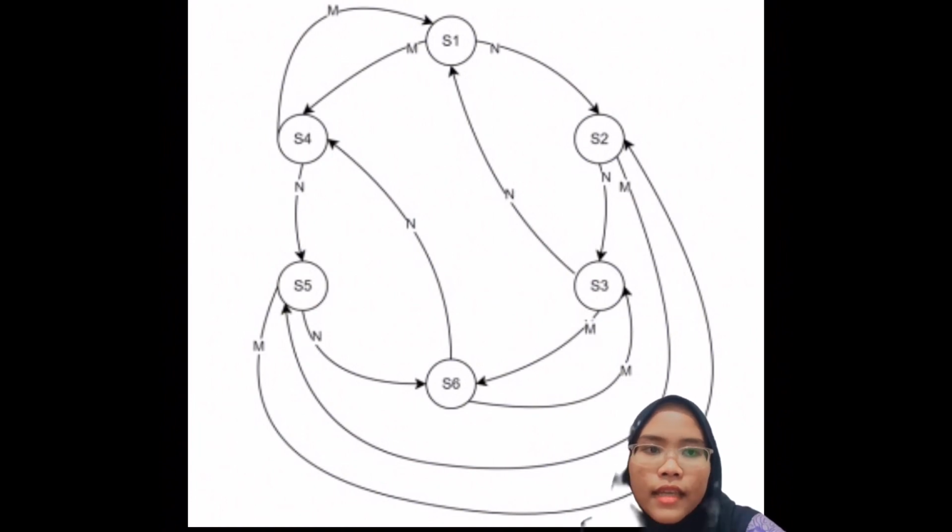During state 6, if the M button is pressed, the heating element is turned off, turning to state 3, where the heating element is off while the steam is generated at high mode. However, if the N button is pressed, the steam generation is reset to off while the heating element is still on, thus it returns to state 4.